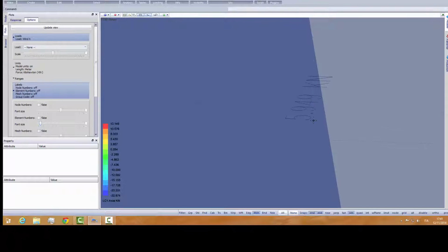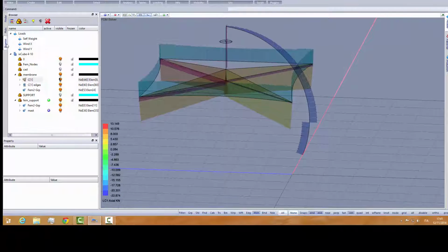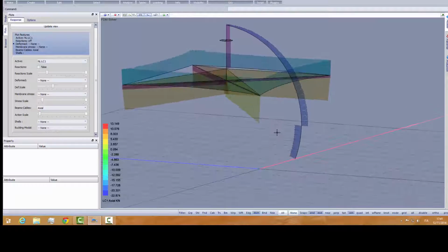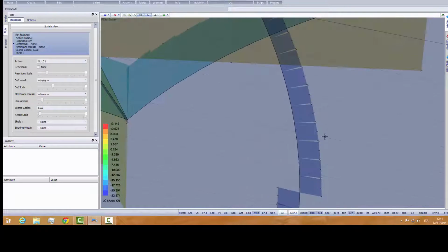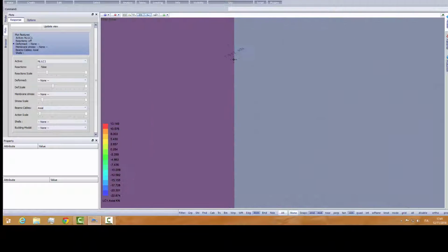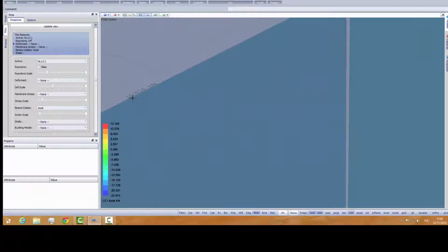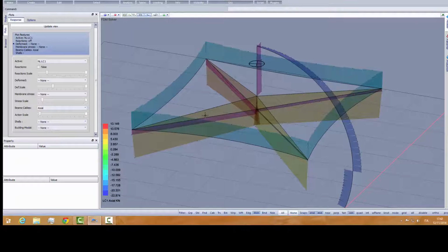And you see that this is the bending moment on the beam, 5.9095 kilonewton meter. Oh, this is the axial force, sorry, these are axial forces. We are plotting axial forces, so these are the axial forces in the elements. So these are in tension. The vertical mast here is negative, is in compression, nearly 8 kilonewtons, and the edge cables have 10 kilonewton. They are prestressed, and these are the axial forces.